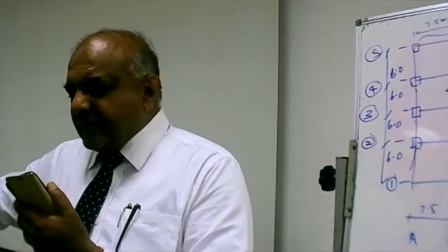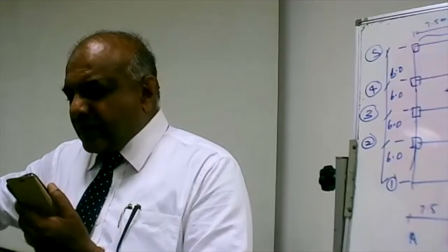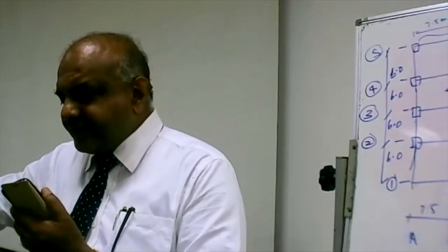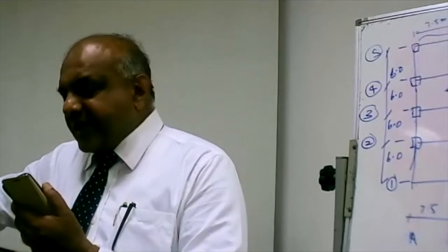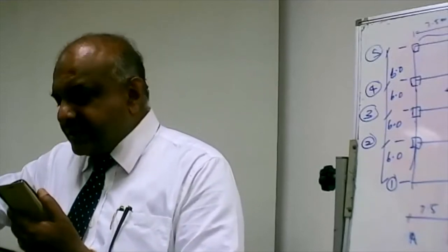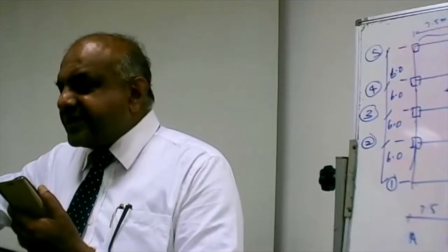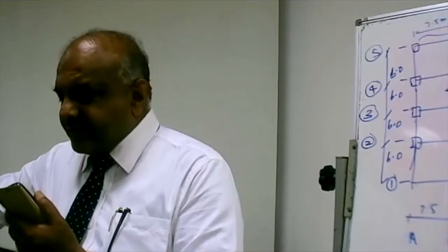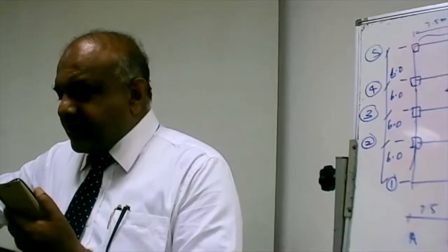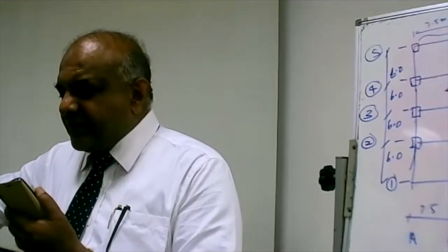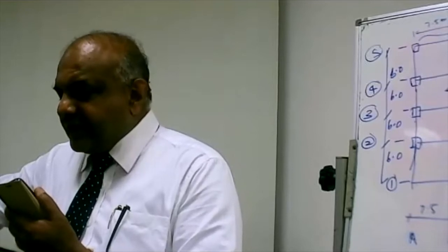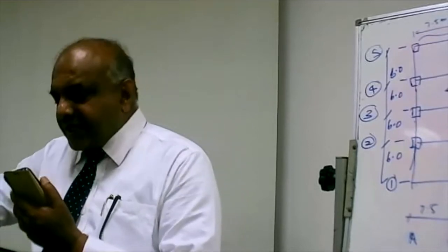So generally, what you have to see is how much accuracy you need for the calculations. The gain you get will be very little, and you will be just unnecessarily wasting your time on doing very serious calculations. So that's why, when you are doing manual calculations, generally, we do not consider the walls in the other direction.